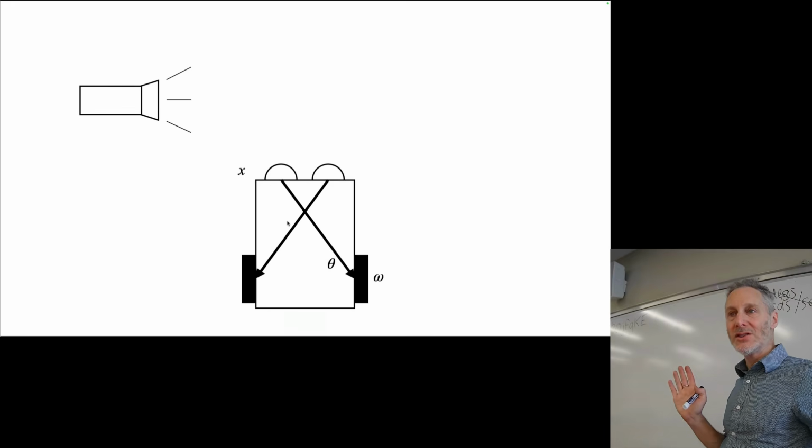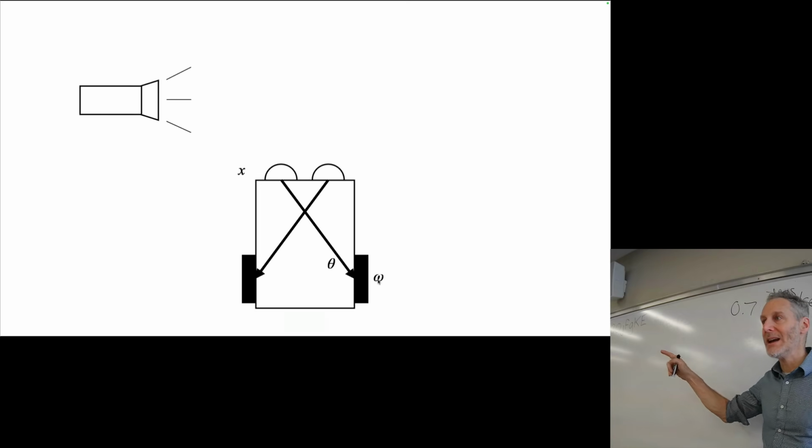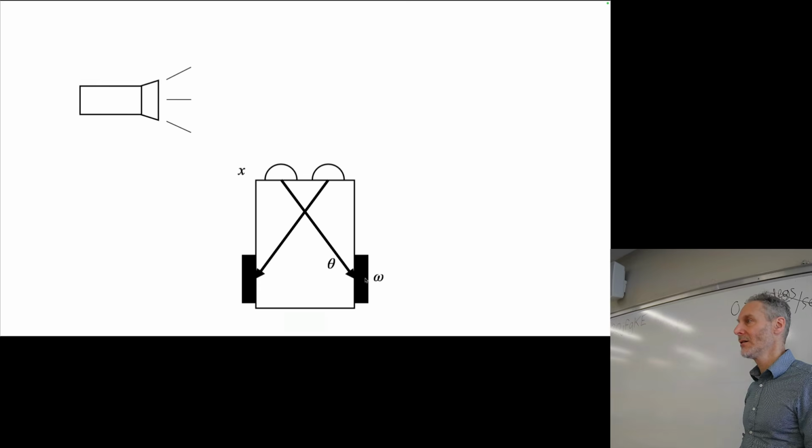Let's think about these 3 parameters for a moment. When we build a simulation of this Braitenberg vehicle, we, the humans, are usually responsible for X. We tell the physics engine where to place the sensor. The physics engine is responsible for computing omega. It's the one that figures out radians per second according to these other parameters. And we, humans, usually set the weights ourselves, or we let the optimizer set them. So we've got different parameters, and different entities are responsible for setting or changing these values.